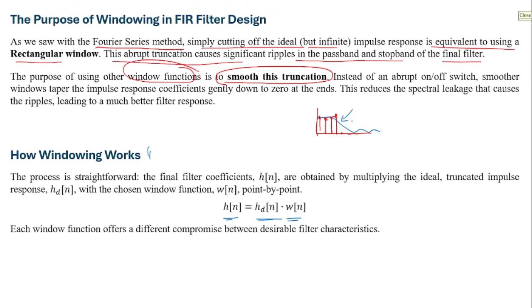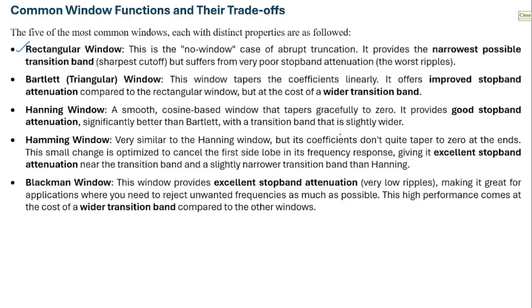band. Transition band is, see, there is a gradual decrease, so if you calculate the cutoff, suppose this is the cutoff, A by root 2, and then this is the stop band. So this frequency from where the stop band starts, this cutoff frequency, and before the starting of the stop band, this band is called the transition band. Okay, it is also regarded as the roll off region.